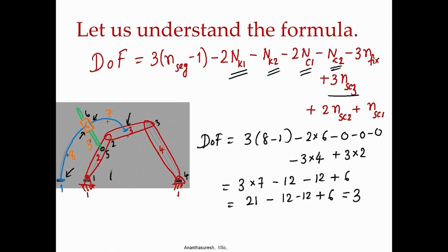The 4 bar that we have here clearly has 1 degree of freedom, that we already know. And after that you look at this green one, it can rotate this way, that way, that is 1 degree of freedom, and the slider can translate. So, we are able to interpret the 3 degrees of freedom in this case in the form of rigid body modes that this has.